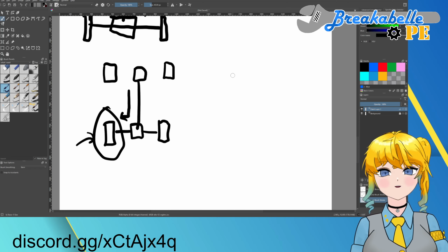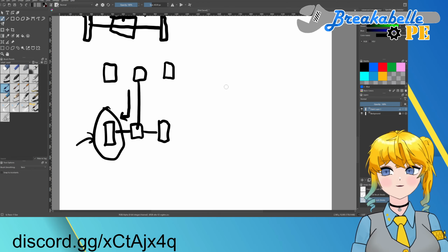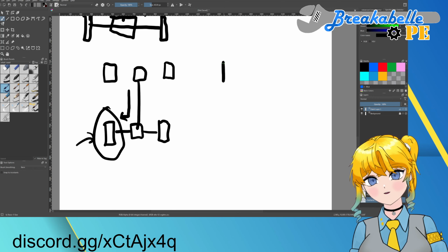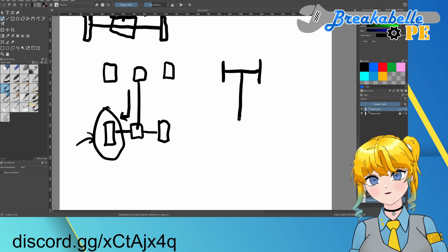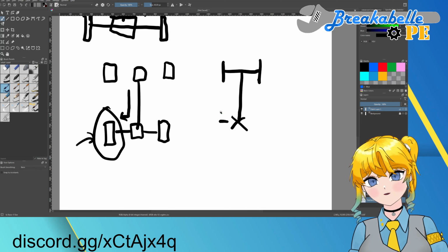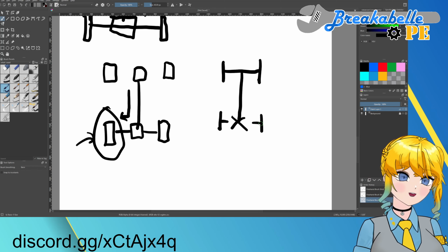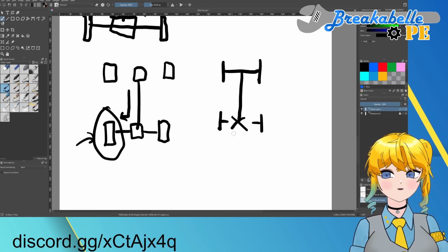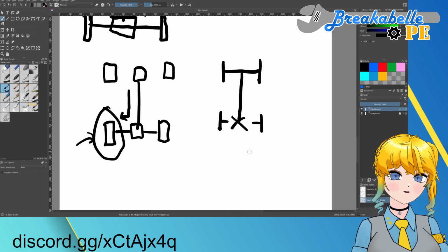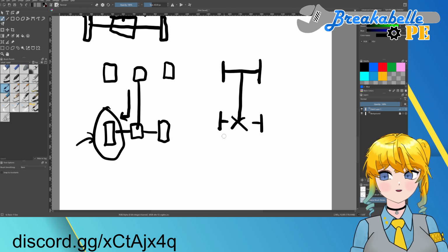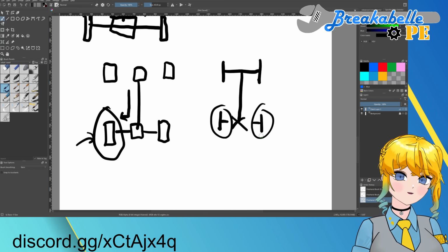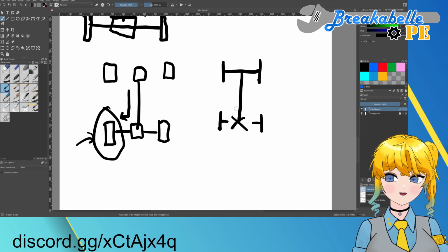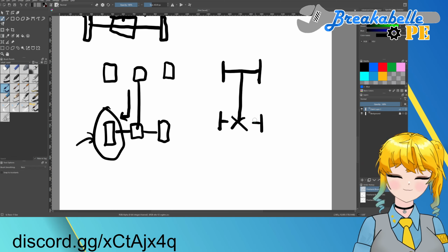So that is why if you have a car made to go off-roading, you might recognize a button that looks like this. And this button locks your differential. So it basically makes your differential stop doing what differentials do, and it makes these tires spin at the same time, right? So however much the right tire spins, the left tire has to spin also when you press this button. So it locks your differential, stops doing differential things, and it spins your tires at the same rate.